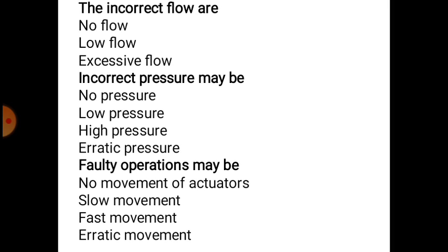Direction control valves set in wrong position. Entire discharge from pump passing over relief valve. So the oil which is pumped by the pump is directly passing through the relief valve and again going towards the reservoir. It is not flowing in the system. And another reason may be a damaged pump.